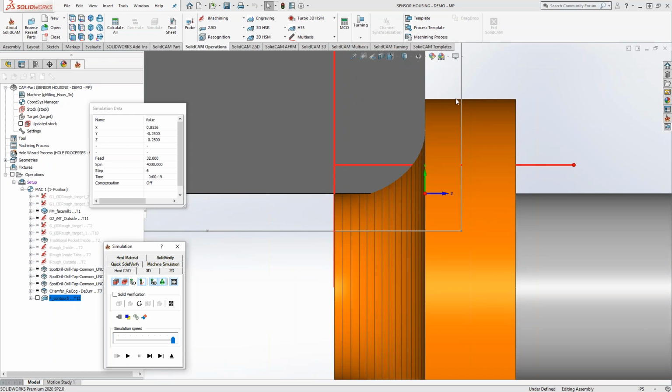If you know your shape tool, you know how much to shift it by, especially if it's an irregular shape tool. And like you saw with the Canadian railings one, it has some odd shape to it. There's nothing on there that actually should be touching the part other than that one arc, that one shape to it. So it's just a matter of when you bring it into your profile or your pocketing or your 5-axis, know the shape of your tool and you know how much to shift it in the axial and the radial direction.